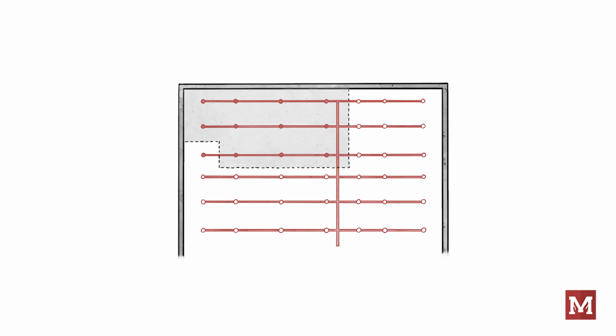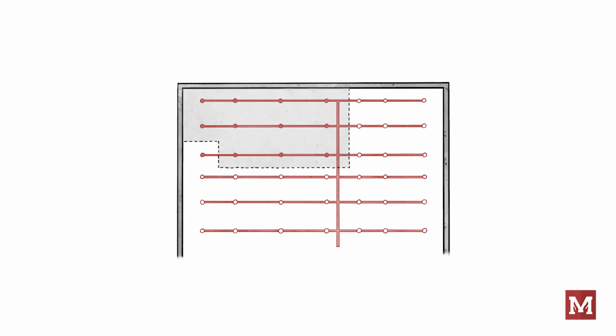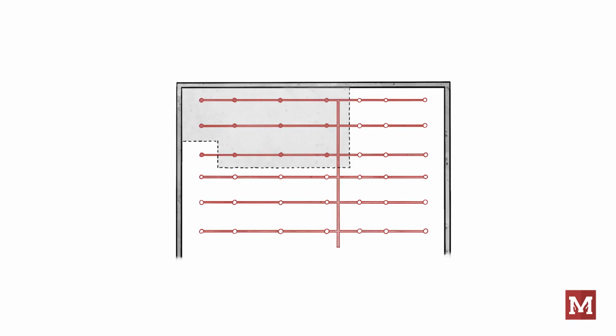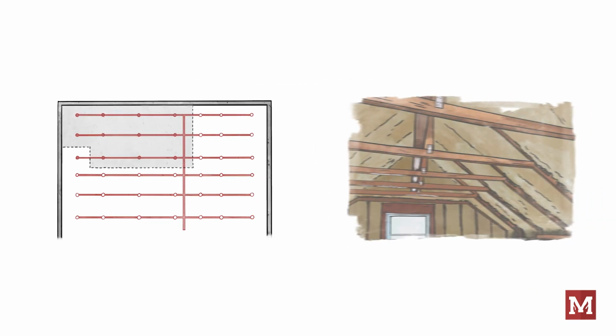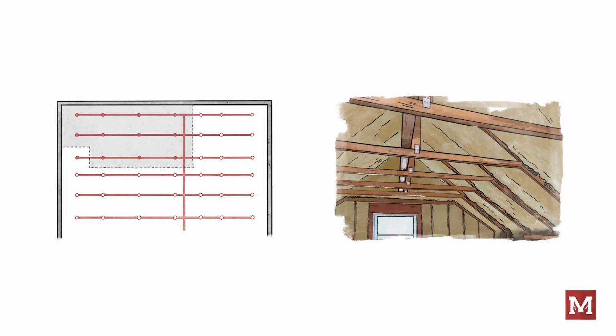Remote area. In the first segment, we discussed the hydraulic remote area and how this doesn't necessarily correlate to the most physically remote area. We also discussed the shape of the remote area. Prior to calculating our system, there's something we need to identify. It's unlikely that any of us are running these calcs by hand, and today's hydraulic software makes it really easy to do this. Now, I do want to point out that throughout this series, I'll use the default remote area size of 1,500 square feet. However, that isn't always the case.